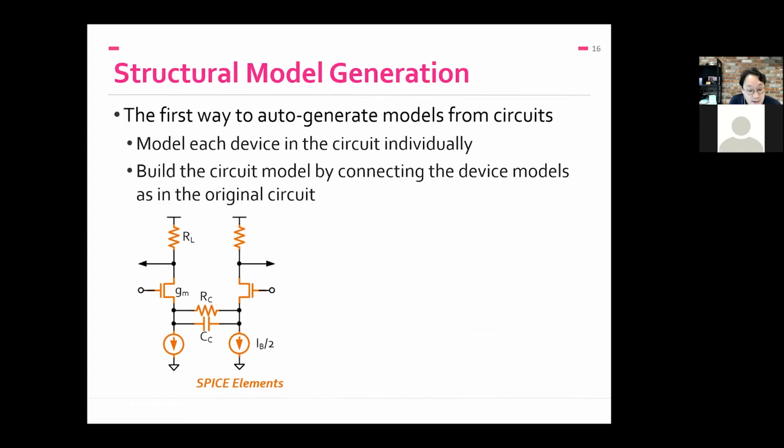For each SPICE element, you come up with the equivalent X model primitive describing its behavior. Like you take a SPICE model describing a transistor, convert that to the equivalent NMOSFET X model primitive, and you do the rest for all the other elements.